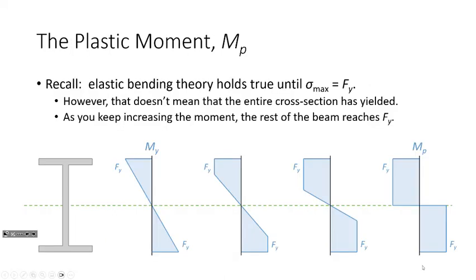No. Okay? The reason why is that the yield moment, and this is probably the most important conceptual point in the whole presentation, is that the yield moment is when the tips hit Fy. That's when we hit Fy here and here. But that's when this hits Fy. Can't this part right here still accept load? Can't this still accept load and this still accept load? Yeah, we can keep loading it.